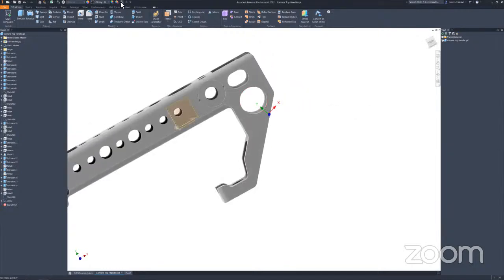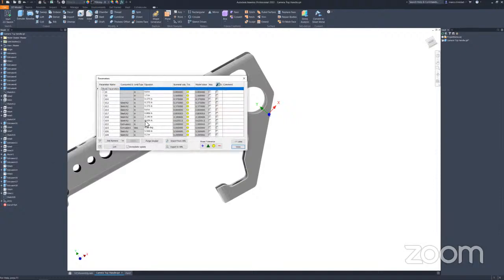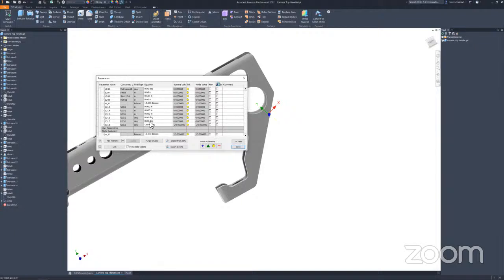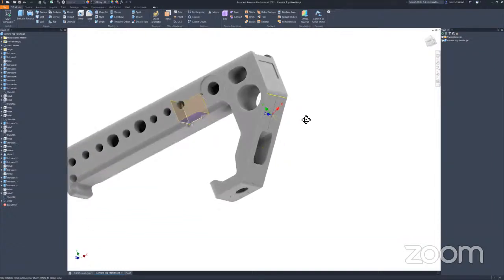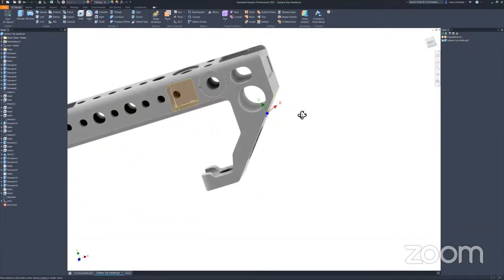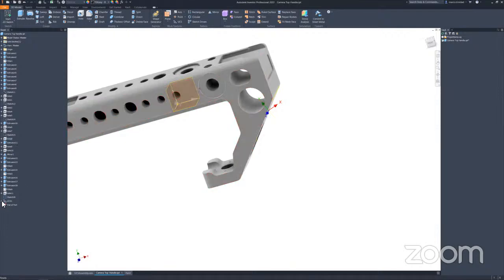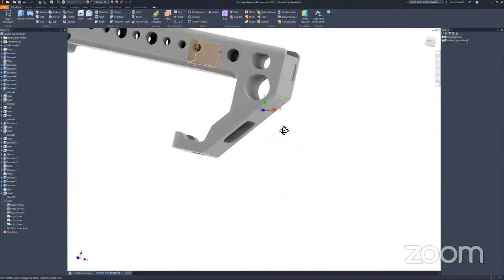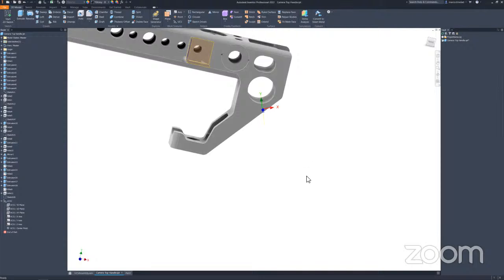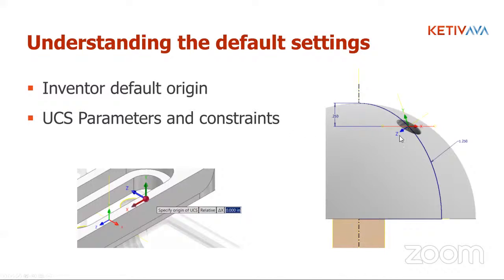I'm going to go ahead and finish that, but I can also edit that same rotation on the parameter right here. Right now, you can see I set it to 20 degrees, and that looks good to me. But if I did want it at a specific angle, I could go ahead and set that. And so an interesting point with this too is that, that angle is specifically not normal to that incline, correct? Yes. So as you can see, like right here, I'm going to go back to my presentation. I was able to place it on this dome feature, which doesn't have any defined features or axes that I could use. Yeah. And then create a skewed hole on that.